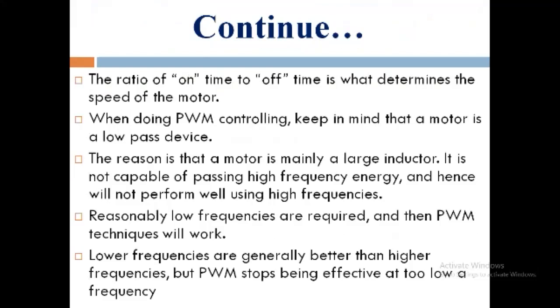When doing PWM controlling, keep in mind that a motor is a low pass device. The reason is that a motor is mainly a large inductor. It is not capable of passing high frequency energy and hence will not perform well using high frequencies. Reasonably low frequencies are required and then PWM techniques will work.